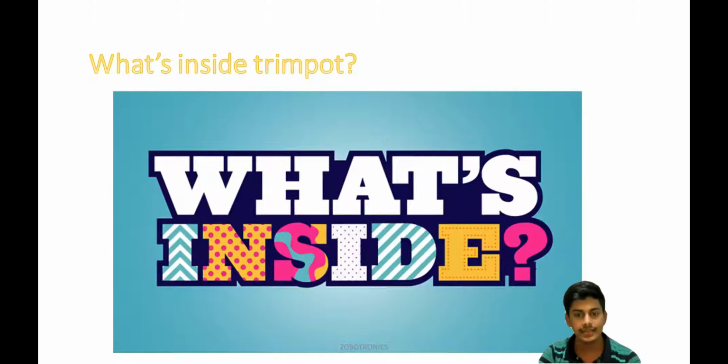So what's inside a trim pot? I will be showing a trim pot. Here you can see the trim pot, which is blue in color. I will be opening this trim pot. It has 3 pins, and it has a knob to vary the resistance. The value of this trim pot is written on the top of it, which is 103, a 10K trim pot. Now I will open it and show you what's inside.